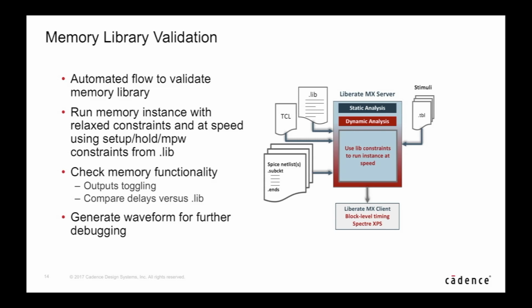And we have a way of generating waveforms for debugging. We generate different outputs comparing the switching behavior of the nodes of interest. Nodes of interest in this case can be nodes that the user specifies manually because he's interested in specific measurements, or a set of nodes that we know are usually important for validation, and we automatically show the results on those.